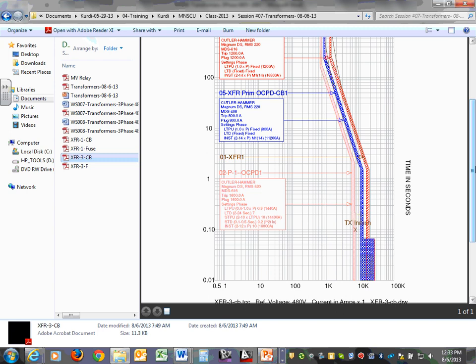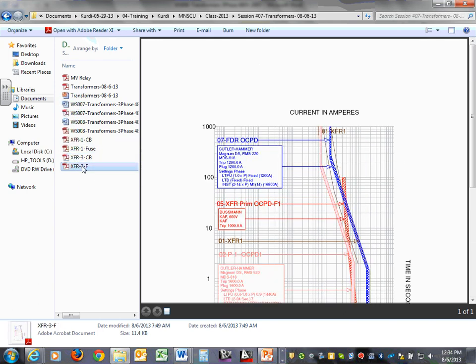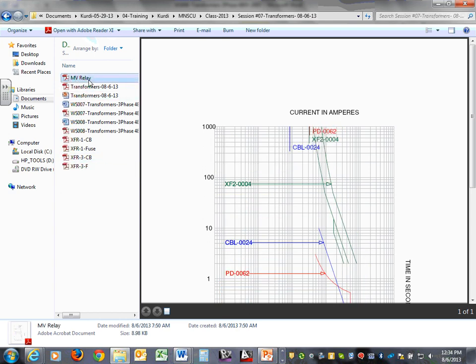So you end up with so-called adjustable circuit breakers. You get into setting up the adjustable circuit breakers and so forth. One with a circuit breaker and the other one with a fuse. So 2 examples, each with a circuit breaker and a fuse, and we do coordination for them. And the last one, I'm going to leave until the end: doing coordination using relays for the transformers.